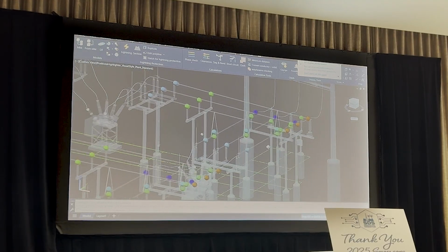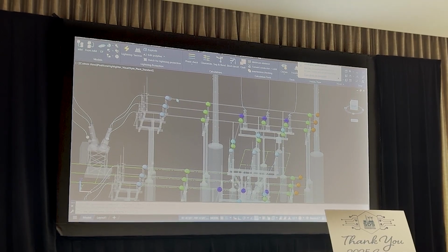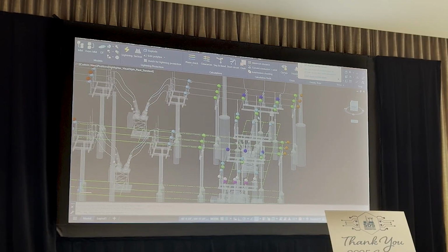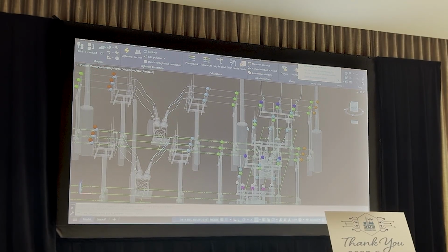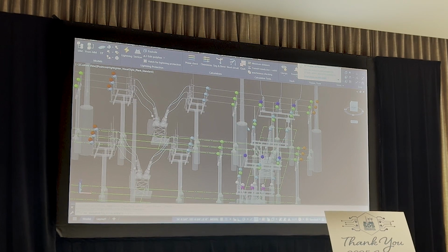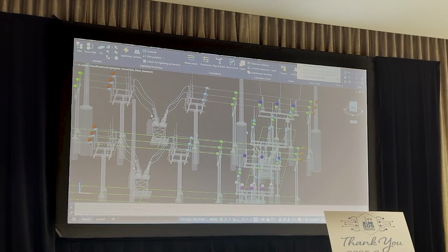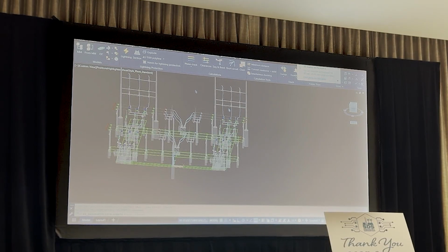Like in this one here, where you have end bells and the bus support clamps and expansion, right? So you can tell it's there on all three phases. Another cool thing this also does, if you ever ran into it, if you accidentally drop something and it goes to the center of your model, which is inside of another object, right? And then you're pulling your bill of material and like, why does it count 7? Oh, it's supposed to be 6. There's one floating on the origin somewhere. This is a real easy way to identify something floating off in space that got accidentally put, right?